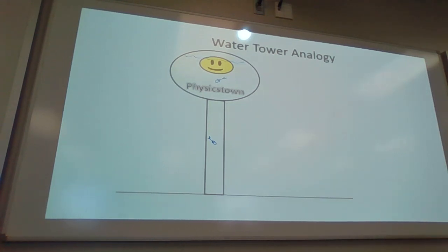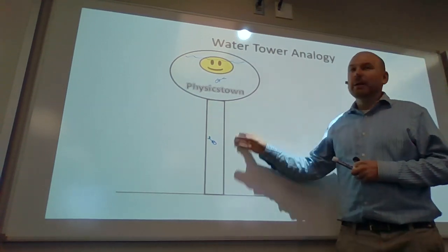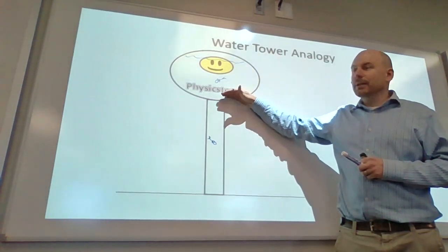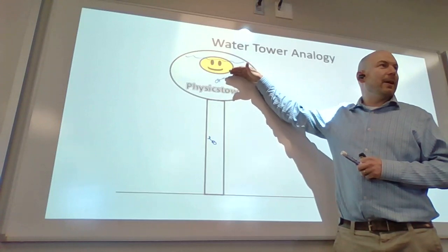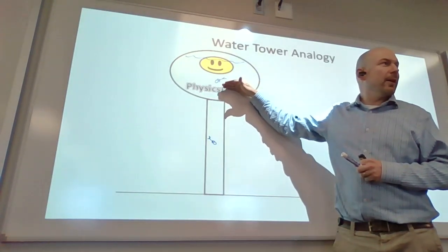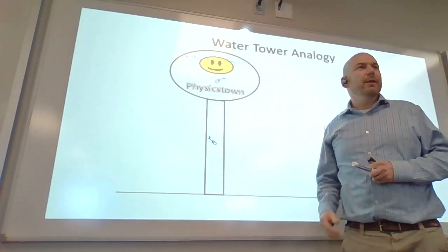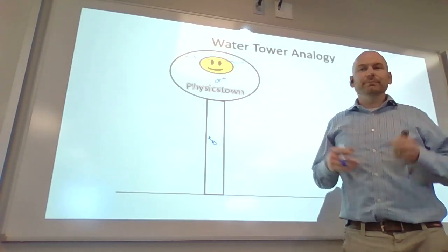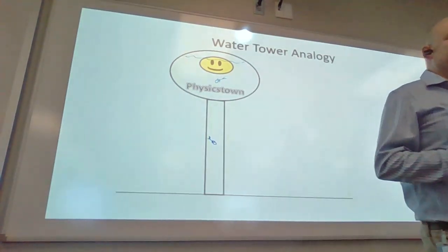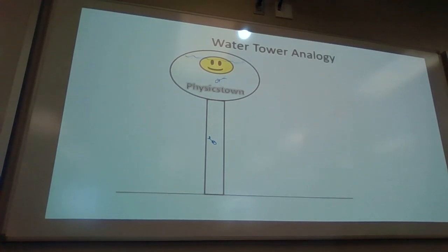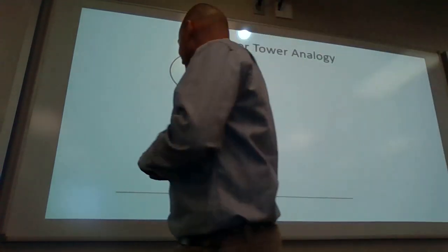And then when it wasn't the peak time, we could turn those pumps off and they wouldn't be being used. The water tower eliminates that problem because you just have one pump continually pumping to fill this up. During the peak times, it drains down, and then throughout the day it fills back up, and then drains. Then throughout the night it fills back up, and so you're always having this constant pressure, even though there's different demands on the system. That makes sense? Okay, so it's a good idea.